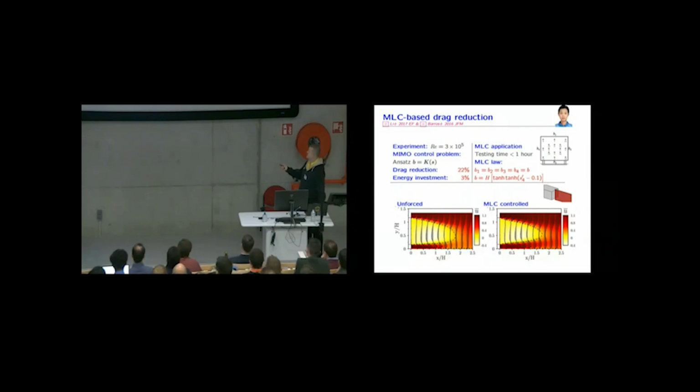What is the physics behind it? Well, we have the actuators here and here. The wake regions, here you see the U component, are approximately the same length, but we reorient the shear layer here. We vector it a bit inward with some actuators. So we make the wake a bit more aerodynamic. And so we do aerodynamic boat tailing, and this gives us a drag reduction.